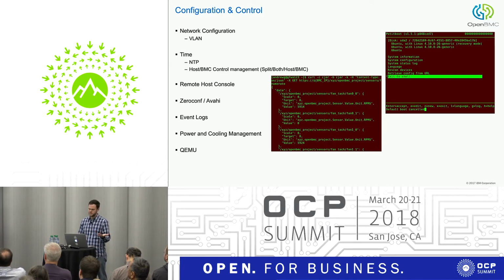Of course, the BMC's got to have power and cooling management. There's, you know, some pretty advanced fan control algorithms out there. I think we've got a new one coming in currently. And then the general ability to power on your systems. I think we were talking a little bit earlier about the system state piece, which is actually just built on systemd. One of the other mantras of OpenBMC is definitely using any open source packages that are available.